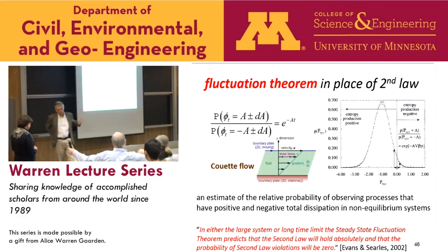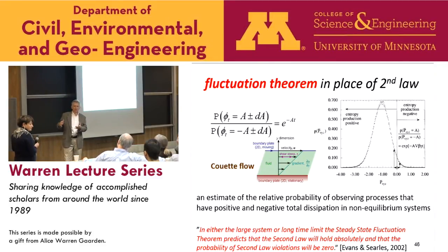Yeah, so what this gives is a scatter of constitutive responses. Because if I do this problem, say 200 times in a Monte Carlo sense, then I have a histogram. I can model some probability distribution. I can invoke some theoretical, say, beta distribution concepts. So that's very useful, I would say. And then I say that this is a stepping stone for stochastic finite elements. Because if I have a macroscopic body, I cut it in pieces. Then unless I have separation of scales for a given finite element, I better have a probabilistic constitutive law.